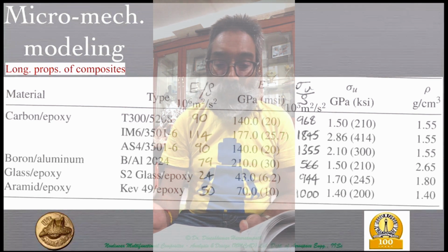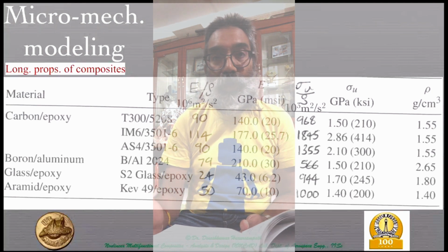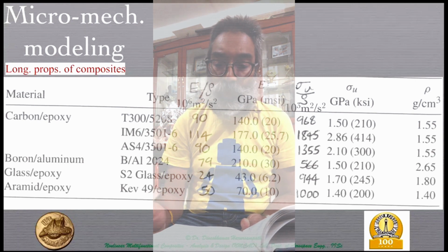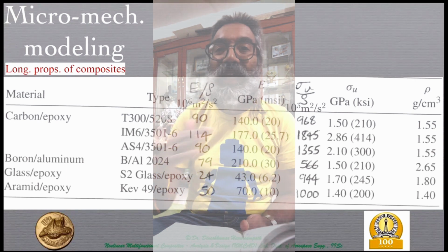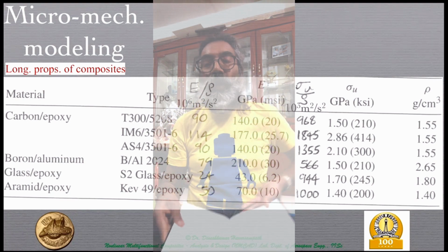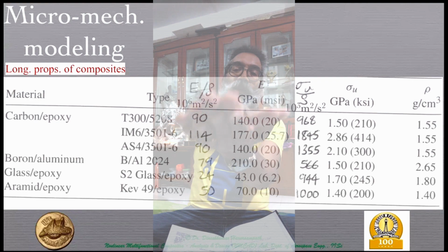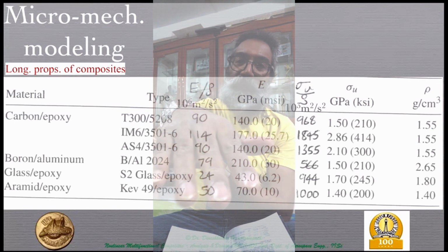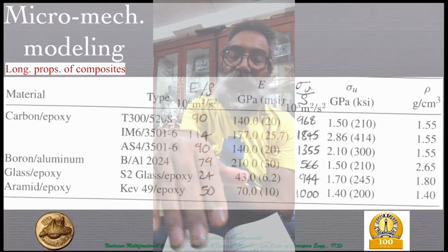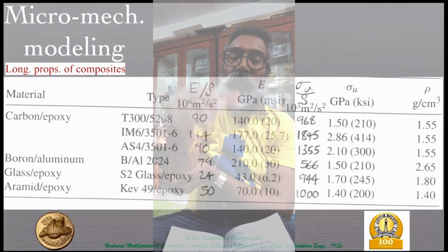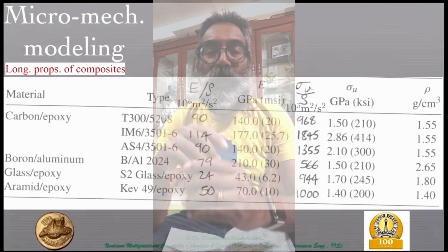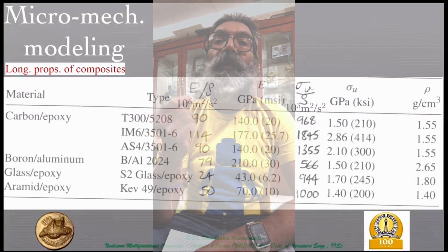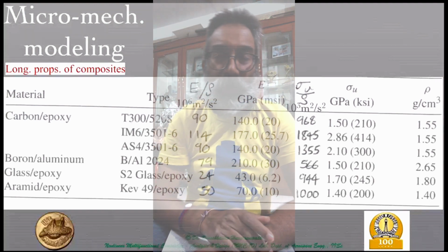So that makes it applicable in certain locations like the fuselage, for example, and the lower wing skins, because they are prone to fatigue because of the cyclic tensile stress that is there. Because the lower wing skin is what is predominantly under tension, except on the ground where a very small amount of compression is there because of the self weight of the wing. But otherwise, it's predominantly under tension, and that value of the tension keeps changing depending upon the phase of the flight and in particular the load factor that is involved. That is how many times the weight of the aircraft is the lift. So based on that, it changes.